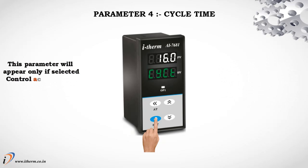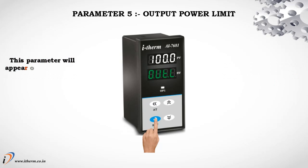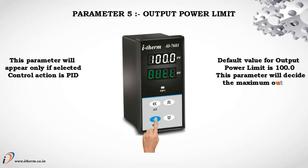Parameter 4, cycle time. This parameter will appear only if selected control action is PID. Default cycle time value is 16.0 second for relay output and 1.0 second for SSR output. Parameter 5, output power limit. This parameter will appear only if selected control action is PID. Default value for output power limit is 100.0. This parameter will decide the maximum output power in percent applied to the load.